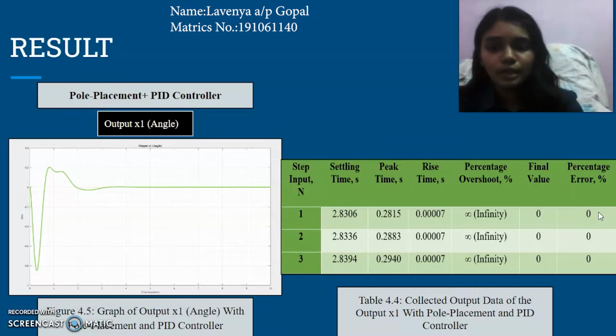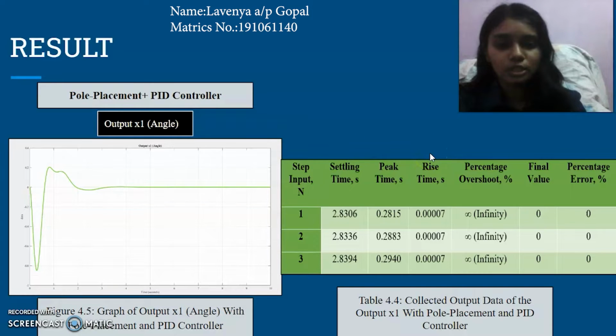So from here, we can infer that both pole placement and PID controllers are beneficial for regulating and enhancing the stability of the system. We can either combine the two controllers or just utilize one controller. Our findings show that after applying the pole placement controller, the output graph for the angle exhibits a stable state. However, the signal starts to provide worse output and becomes more unstable after the PID controller is applied to the system once more. We may therefore conclude that since the output angle has a good output after applying the pole placement controller, there is no need to apply the PID controller to it.